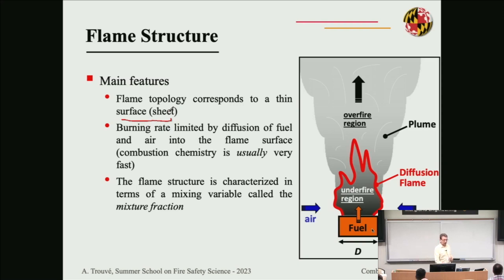The other practical aspect, and an important conclusion from this discussion, is that if chemistry is fast, maybe I can ignore it. So combustion can be viewed as a sequence of two steps. You take the fuel and the oxygen, and you have to bring them to the region where it's hot so they can react. They have to meet, and they have to meet with some heat. So there is a transport, a mechanical step associated with transporting the fuel and the oxygen to the flame.